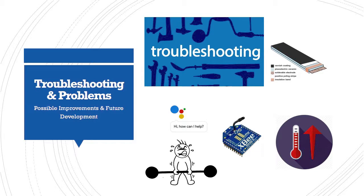The main problems that we faced were in the software development stage. One of those problems was pairing. Our initial approach involved searching for all Bluetooth devices nearby, which was unreliable and slow. We decided to use a new method to pair with devices that were already connected to our smartphone through Bluetooth previously. This made it much easier to find and successfully pair with the correct device. We also did a bit of debugging, especially with using Google Voice Assistant and transmission of messages between the phone